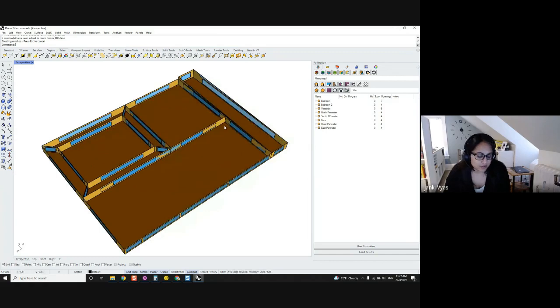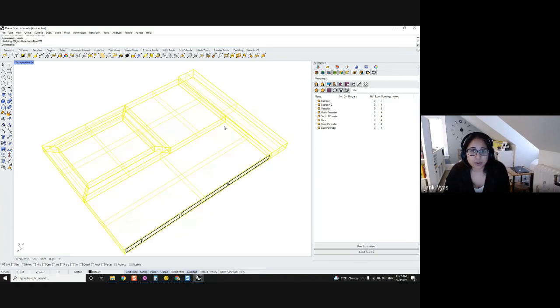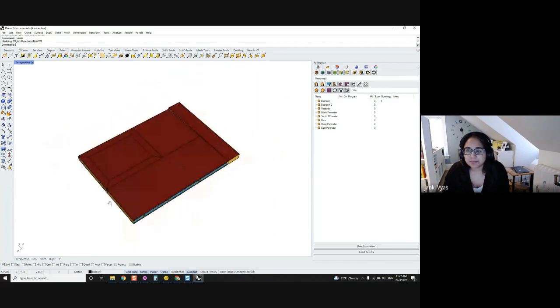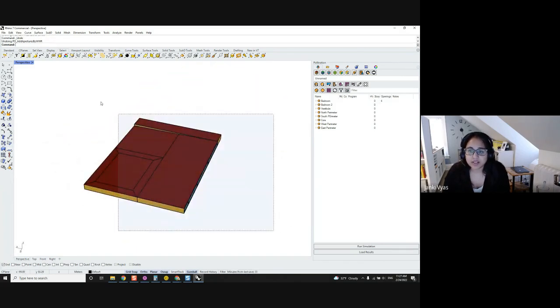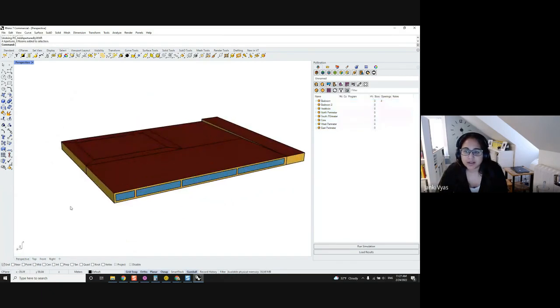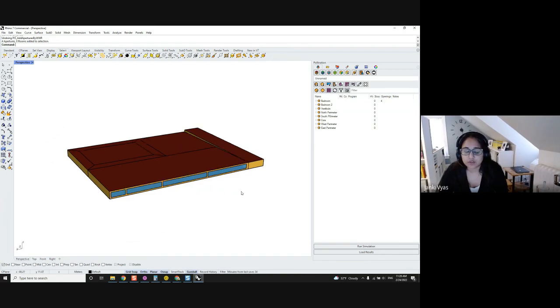We don't want that. So in Rhino, we support Control Z, which undoes everything, which is really cool. And then we can select everything, and you might have missed it, but it didn't add windows to the rooms where it was drawn using specific size. It only adds it to walls that don't already have apertures.